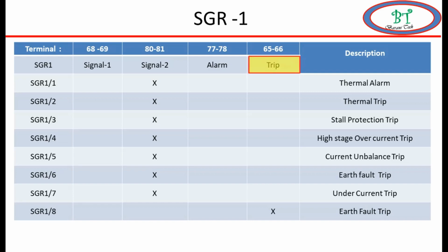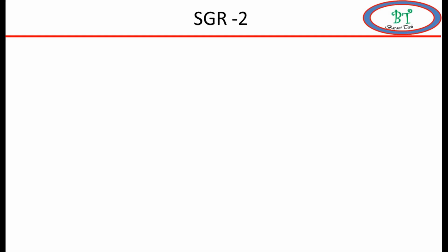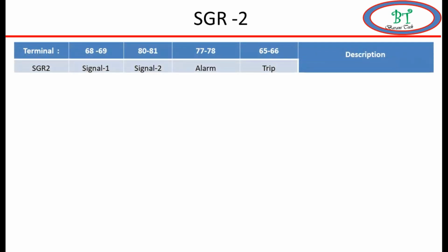So if we are not configured over here, even though we keep the settings and the LED will operate, the relay will not give protection trip for earth fault. So this is very important. Now we will see SGR2.